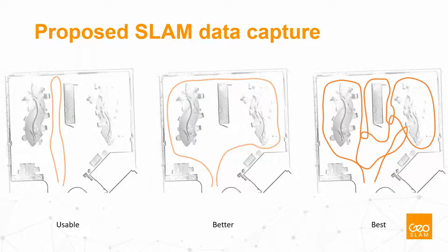Suggested capture time for each system is 20 minutes. This way you can process it on a processing computer with specifications listed on the GeoSLAM website. So something of at least 16 gigabytes of RAM and a good processor.